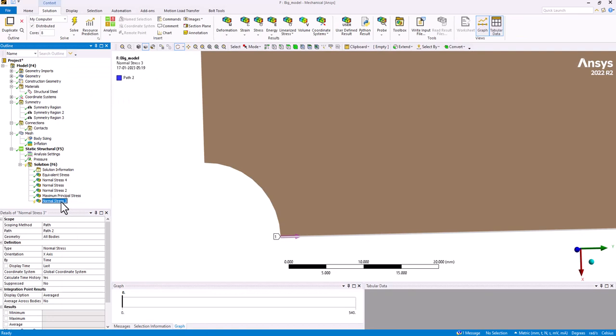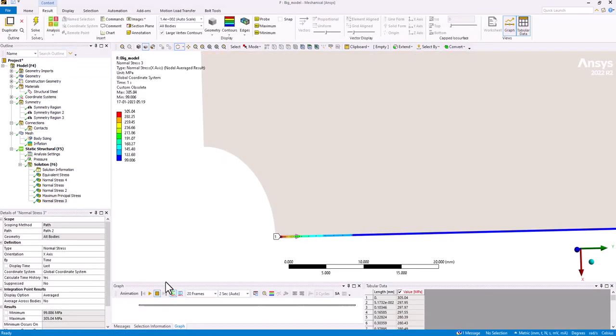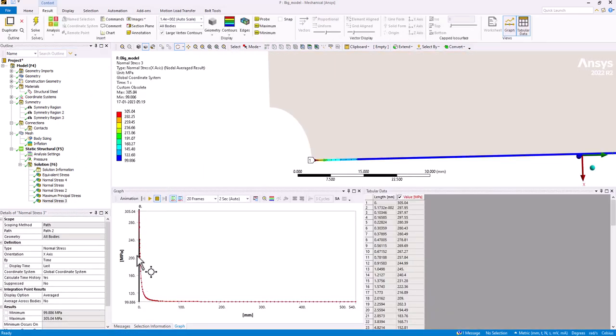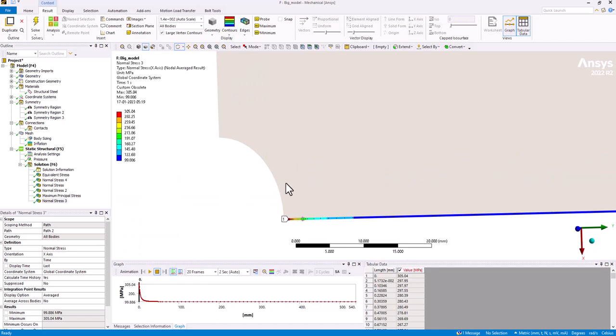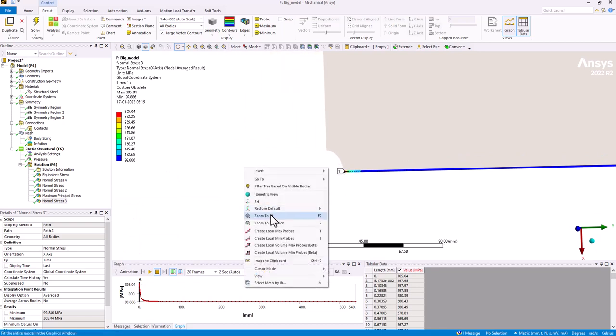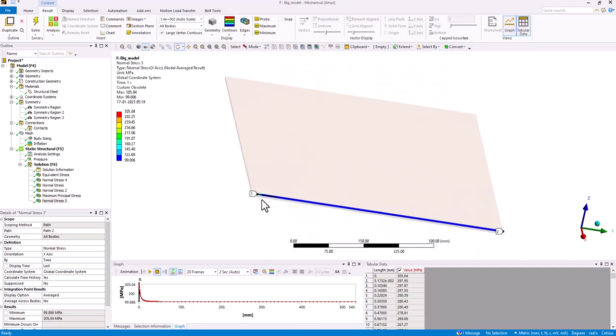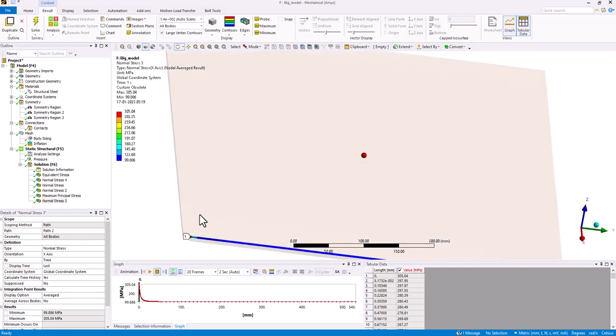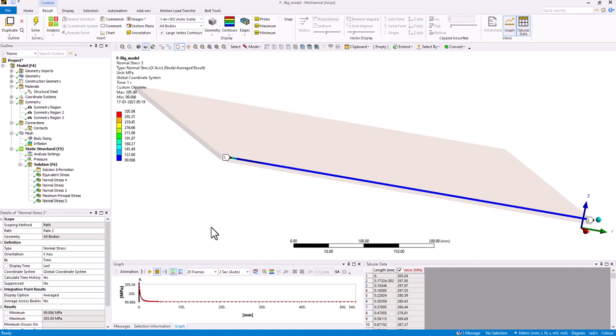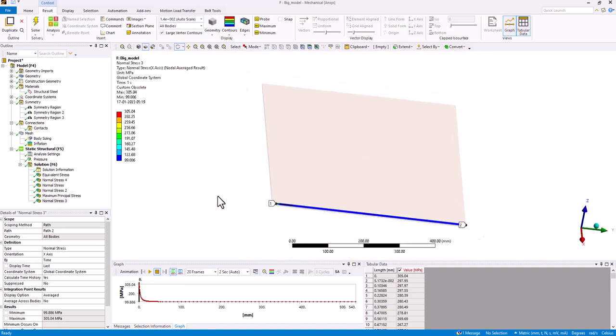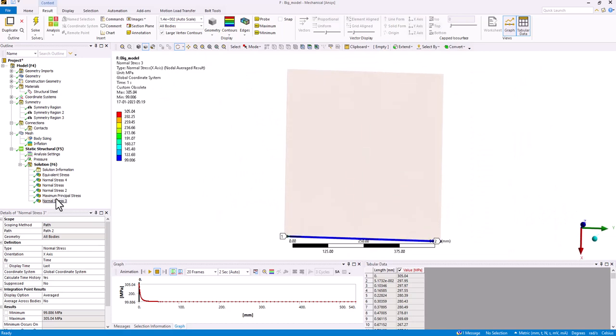I think if we convert it to a path, we'll get a little better clarity. So you can see, starting at 0, it's 305.04 MPa. And if you further increase the computational domain, it will match more closely with the analytical value that we usually get, that is, stress concentration of 3 for uniaxial loading for an infinite plate with a hole.